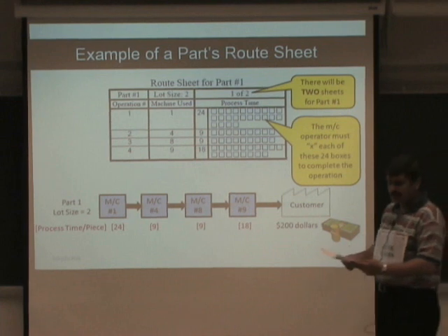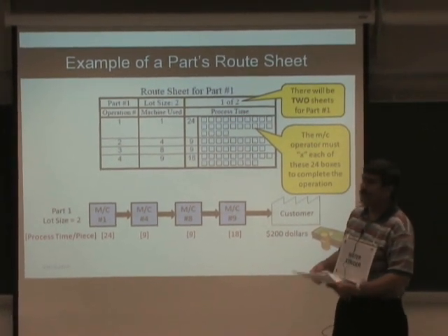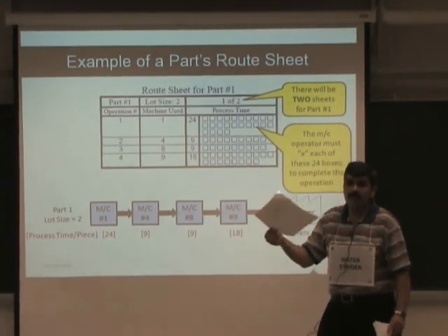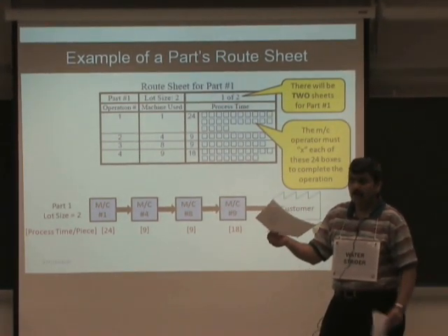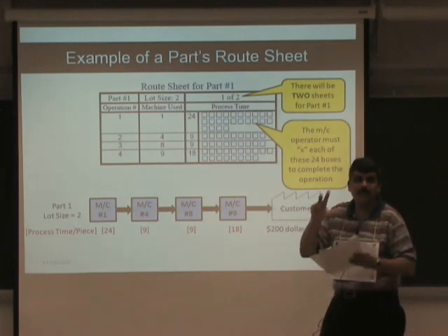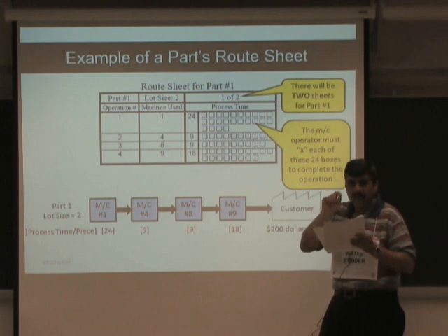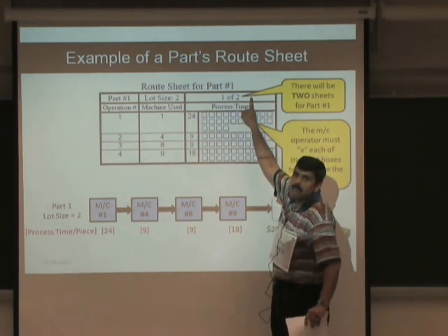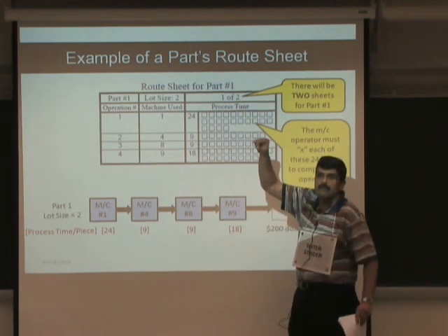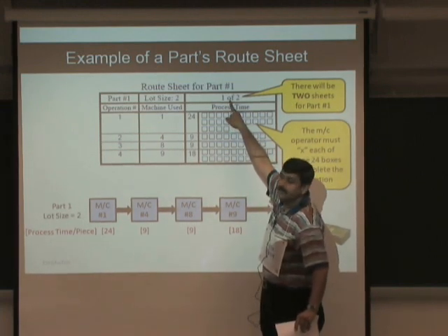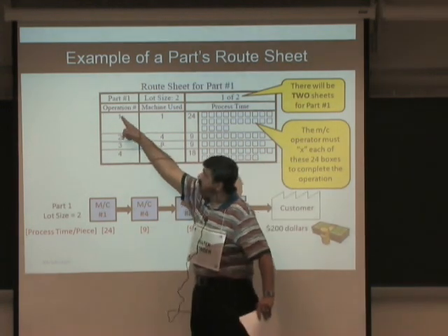So, for all the machines, this is what you should work with, okay? This is going to be the route sheet. Now, when you get a route sheet, kindly check for batch size. If you see a staple or a paper clip, that will indicate 2 to 3 pieces in your batch. So please be diligent and check for that. Look for this number. This is typically how people describe individual pieces: 1 of 2, 1 of 10, 2 of 3. They're trying to keep count of the piece count. So first of all, check this number. Then, that's your operation sequence.